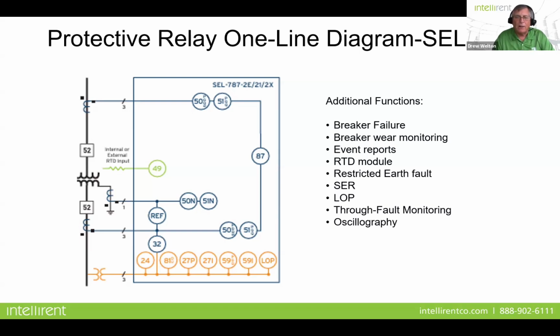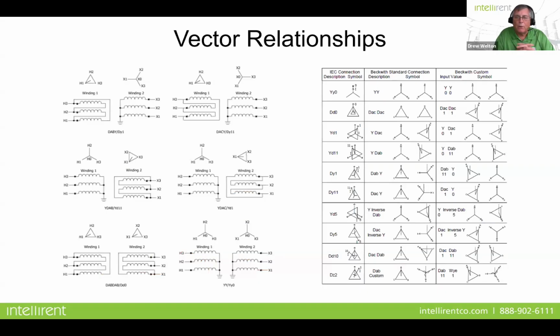Now, between the two relays that I'm illustrating today, one of the things that's very important to understand when you do relay settings, or if you do relay testing after the settings are present, or even if you're out doing maintenance testing on a transformer, is the transformer connections and how it's connected to the system. And usually, this is of course always present on the nameplate of the transformer.